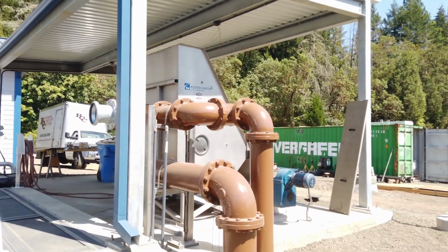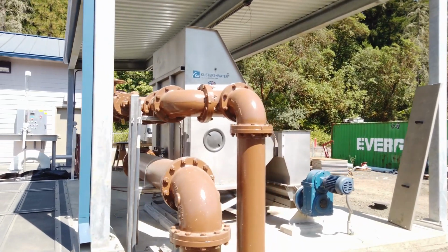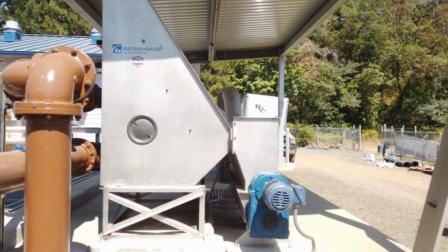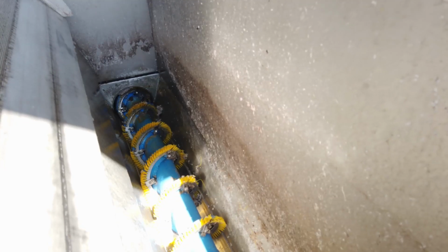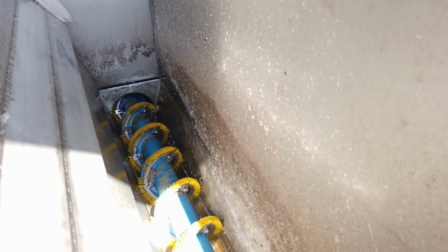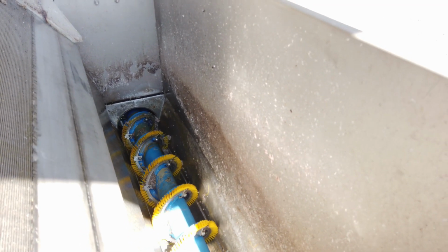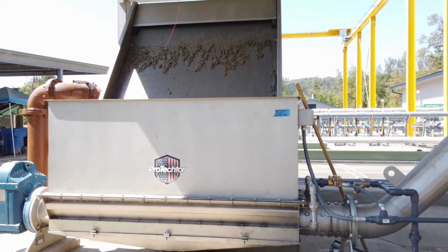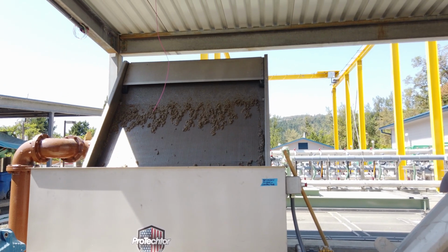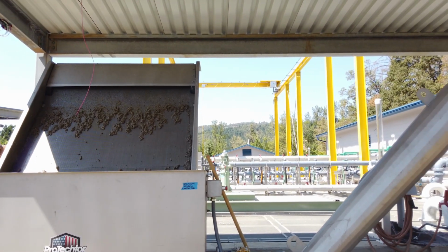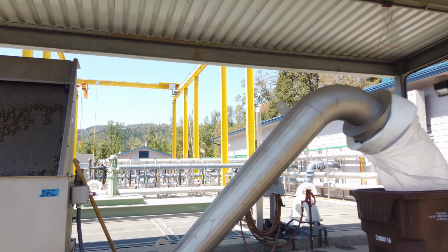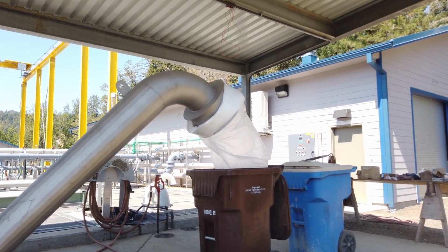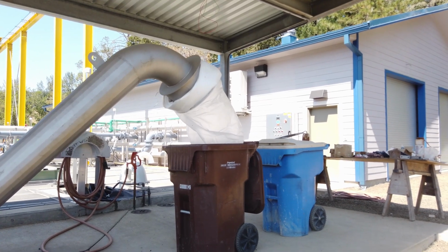The secondary screen is a side hill screen that processes influent wastewater that has already undergone removal of particles 3 millimeters and larger. Particles 1.5 millimeter and larger collect on the screen, accumulate, and slough off into a washer compactor. Sloughed solids are washed, compacted, and conveyed into a continuous bagging system for eventual landfill disposal. The side hill screen can be physically cleaned with a squeegee as material plugs the openings. This is a relatively quick maintenance process.